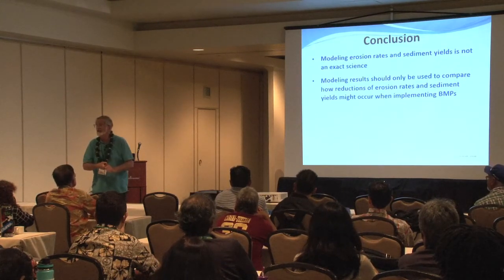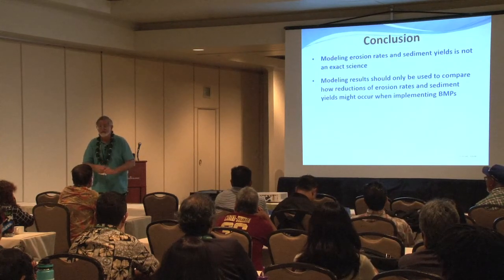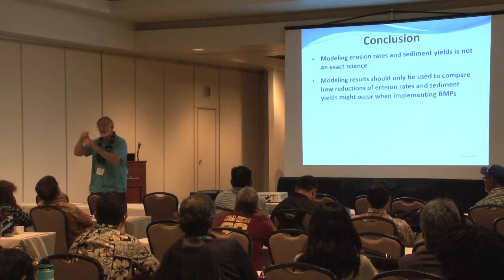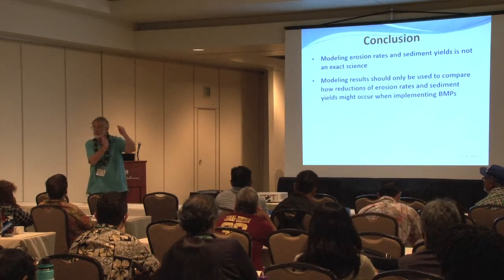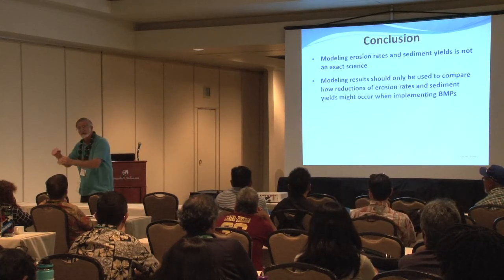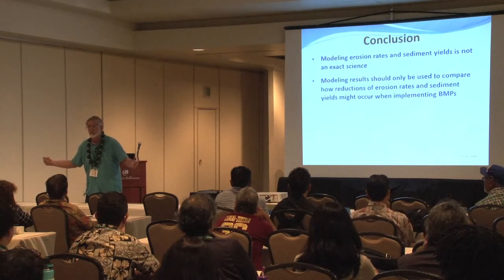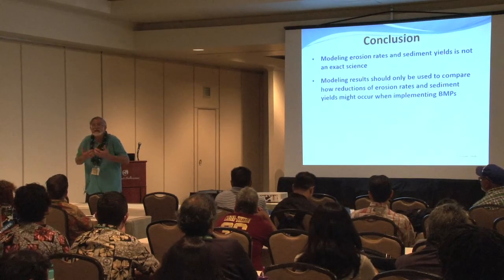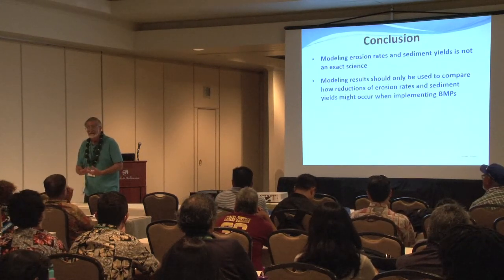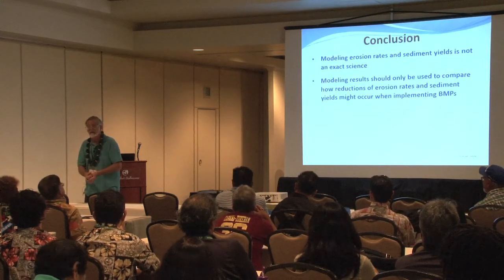Is hydrology an exact science? Anybody who's ever done hydrology knows you take some numbers over here, a CN number over here, we're going to use that number over there, we've got a slope length here. I like to make it 230 feet. Oh no, I like 250 feet. No, it's got to be steeper. Everybody in this room can have a different value for a peak flow. It's not accurate, but it's the best we have. Erodibility, it's not accurate, but it's the best we have.